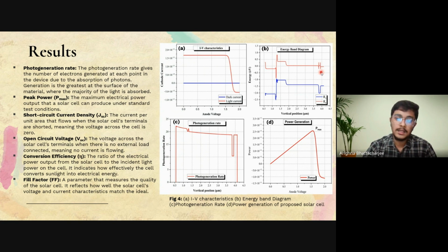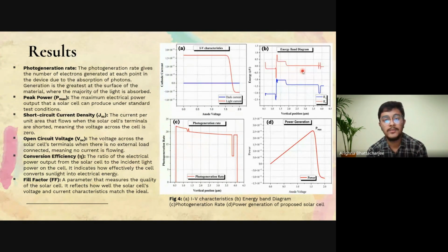This is the energy band diagram. To conclude, the studies given by us show that the indium aluminum gallium phosphide used as a window layer provides a very optimized fill factor of 88% and quite generous 25% efficiency in the solar cell.